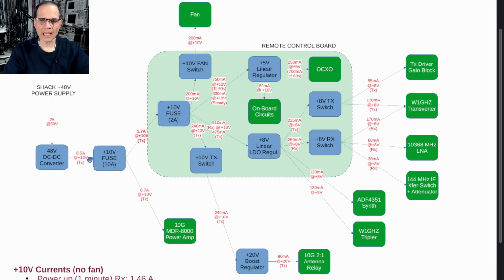So roughly 8.5 amps at 10 volts in transmit mode. So I will fuse that 10 volts. 10 amps is a little too close for comfort. I will probably use a 12 amp fuse if I can find one.